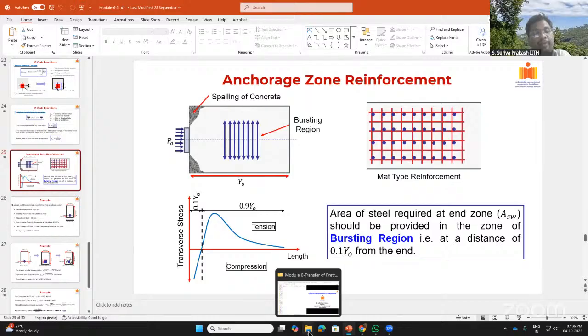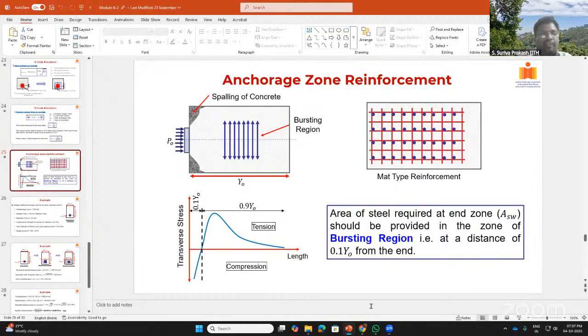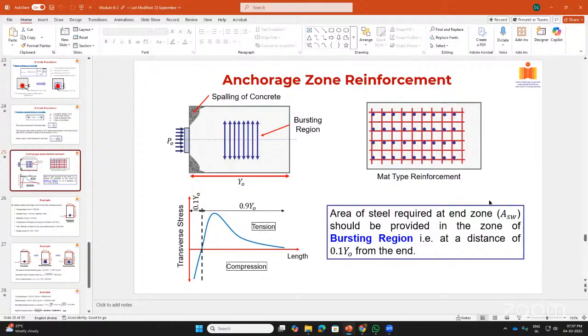But will it be able to achieve that very quickly over a short length? I don't know, because how that bulbing is done and what the spacing is, all those things will play a role. But let me check the codes and come back to you. That's a good question. I'm really not sure how it will play out. If this is not creating the proper development length effect, then we have to restrict the PT percentage amount for calculating the negative moment resisting capacity near the dead end.